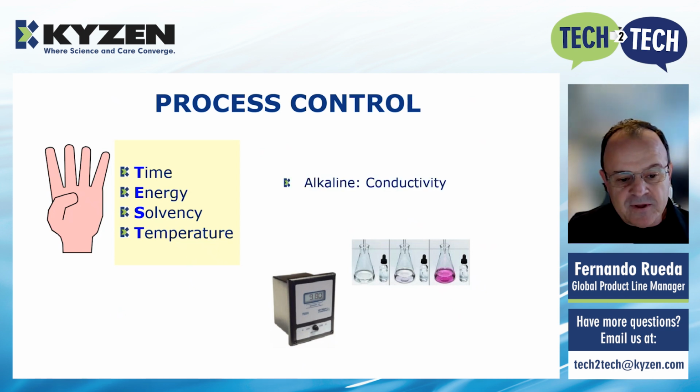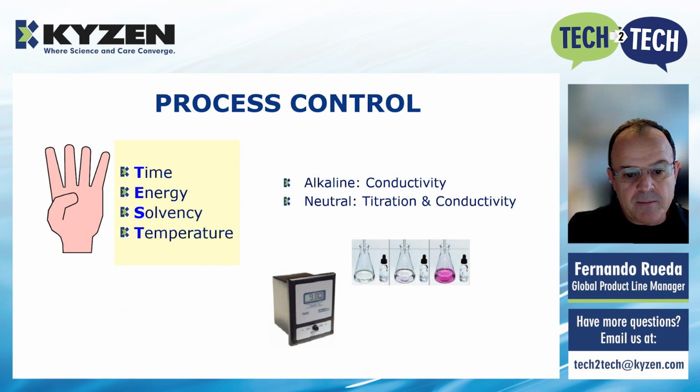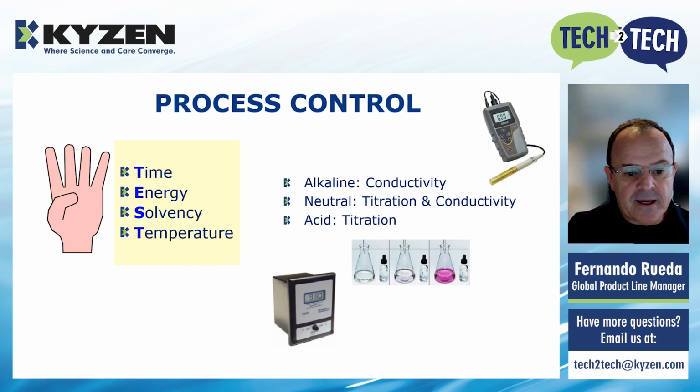And we have different ways of controlling, especially the concentration, the solvency aspect of these parameters. Alkaline products will be monitored with conductivity. Neutral products can be monitored via titration or conductivity. And acid products have to be monitored through titration.